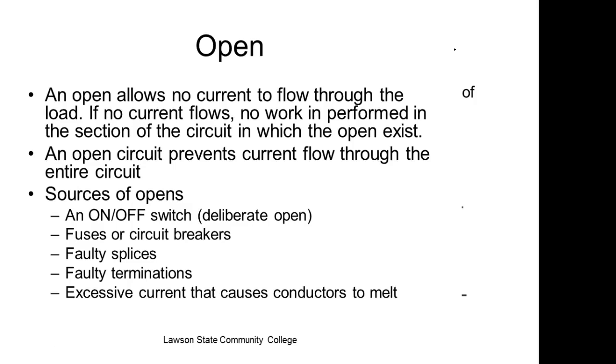So I've seen that happen before. People run wires, they don't leave any slack in them, they run them real tight. In house wiring, you're supposed to have at least 6 inches of slack coming out of your wall out of your box, right?